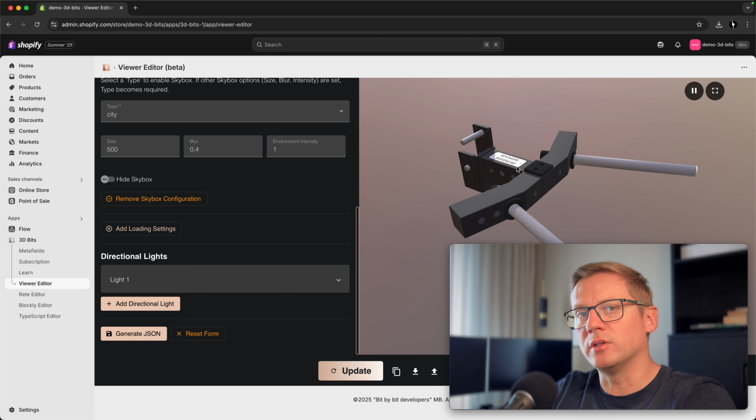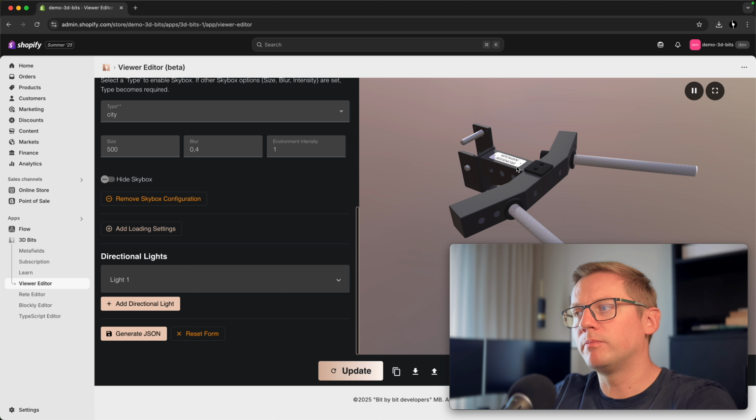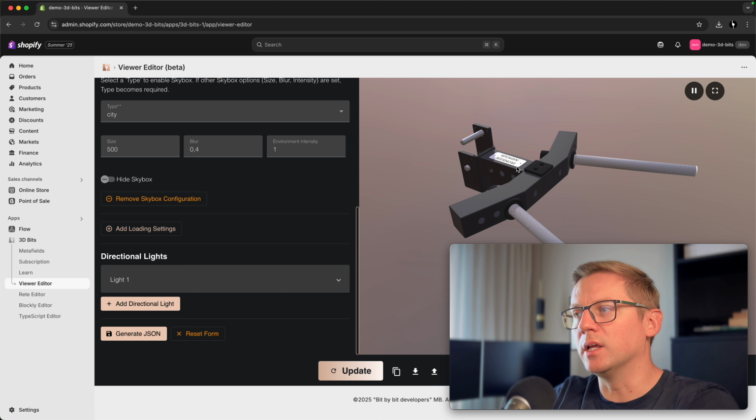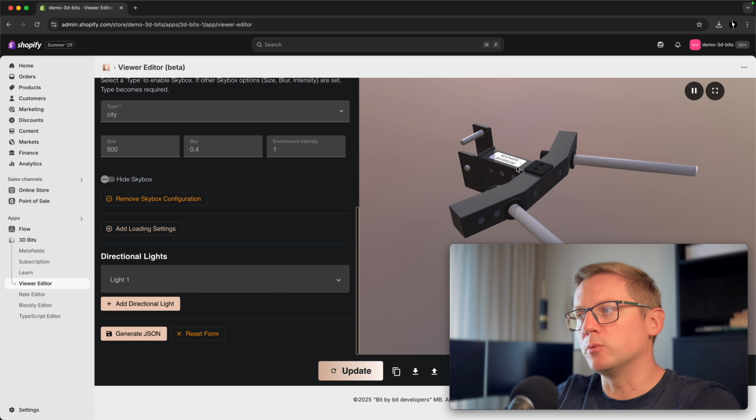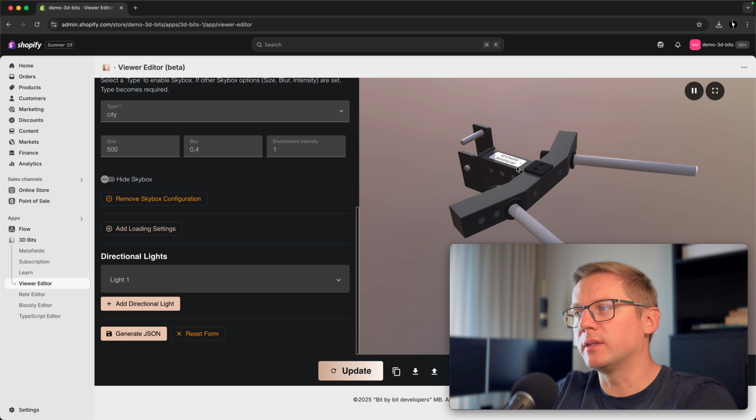Especially this method is useful if you have a lot of meshes, so merging those parts is really beneficial for performance. We already saw one part which we downsized to 6 meshes from 1000 meshes, and performance really improved. The frame rate of the configurator increased substantially.